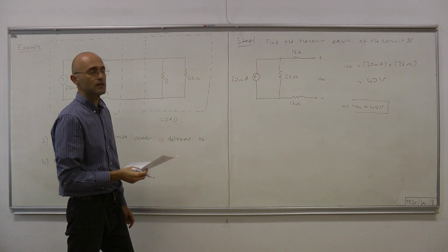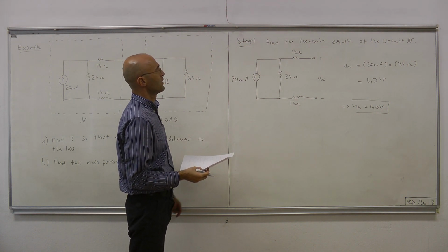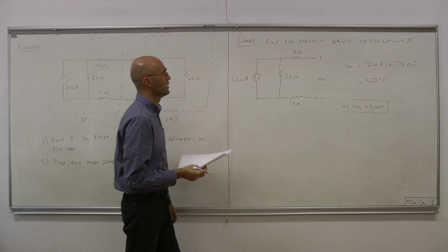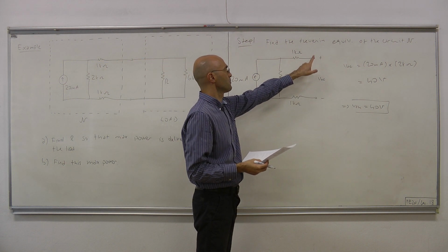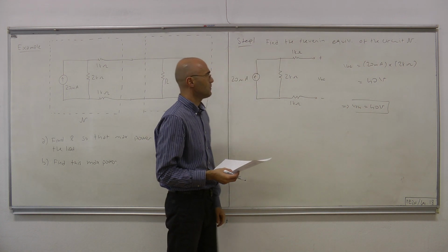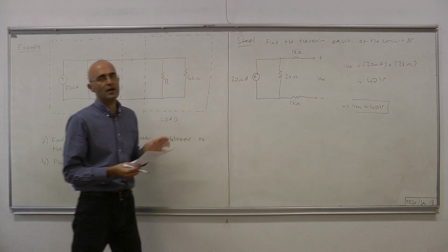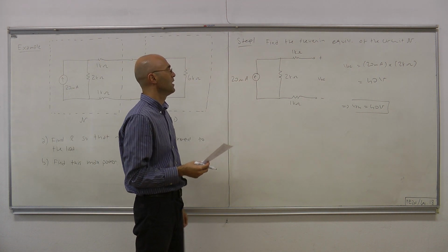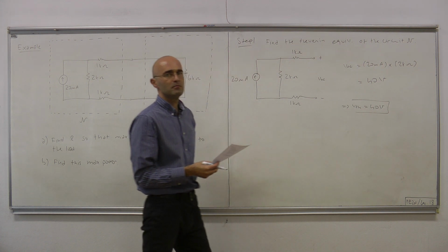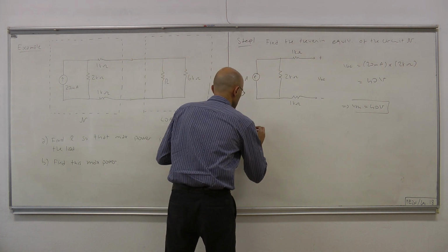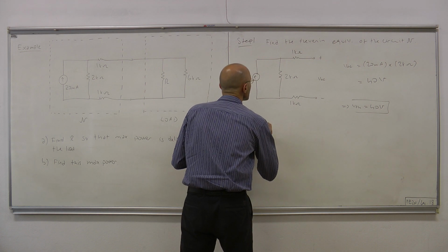And then what we require is to figure out the Thevenin resistance, and for that we could either compute the short circuit current and divide the open circuit voltage of 40 by that number, or, since in this case the topology is quite straightforward, we can kill the source, that is replace it with an open circuit, and compute the input resistance seen from those terminals. So let's do that.